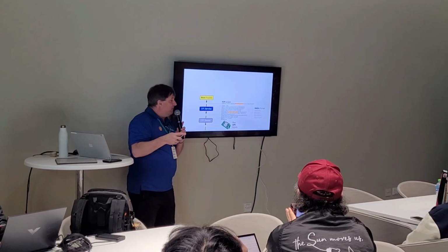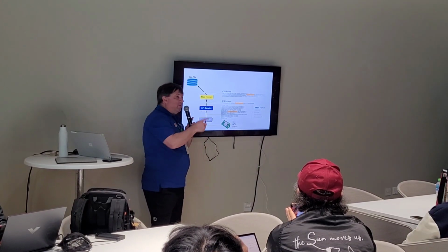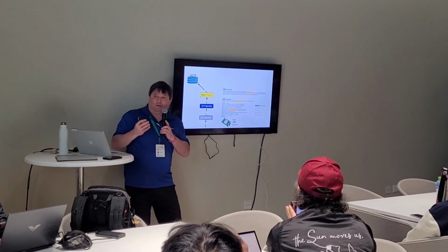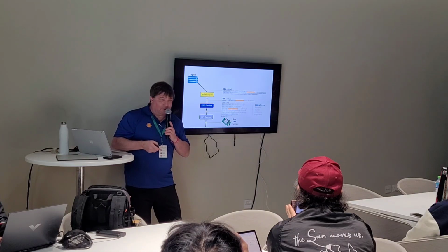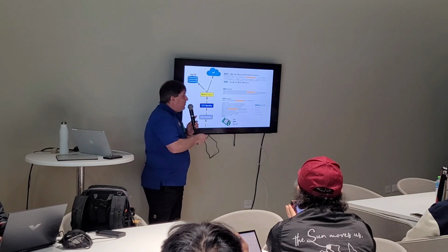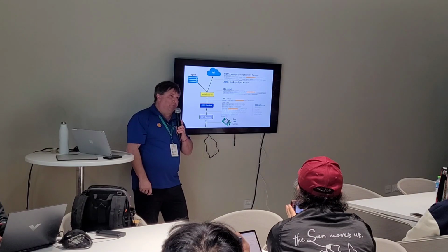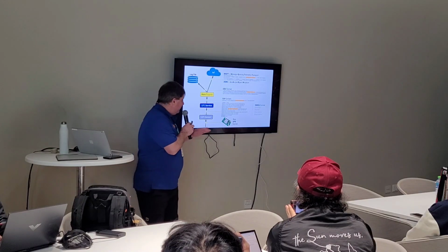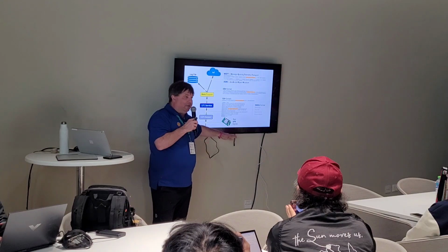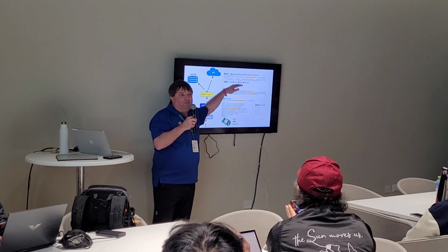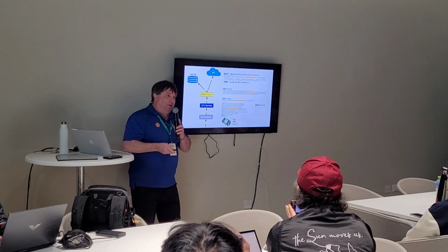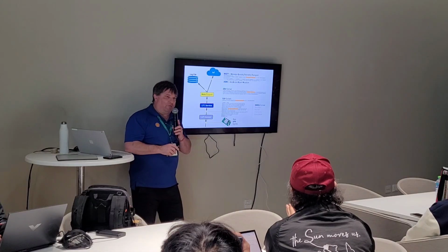Through the TCP sockets, and then from there on we create the CSV file on an SD card, a local data storage, and we put it into a JSON string and MQTT to a broker. So here you can see all the levels from acquiring the data up to the cloud and to the local data that you can then read out, for example, through Wi-Fi.